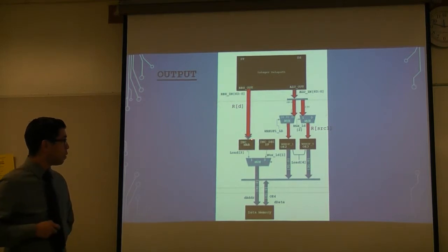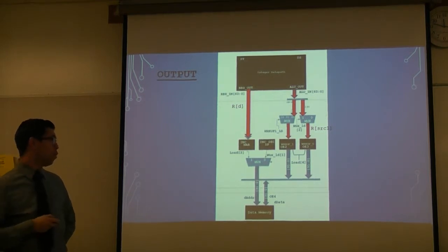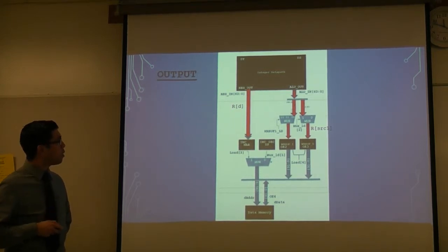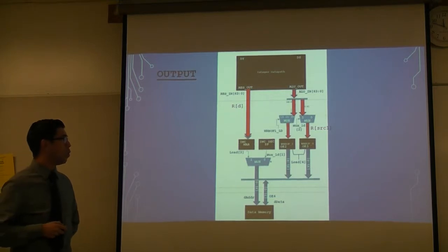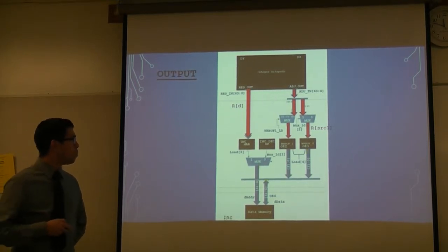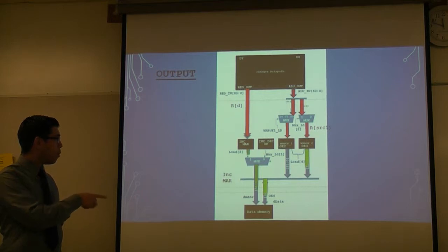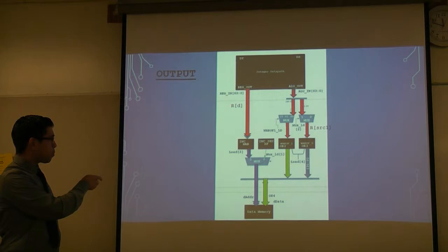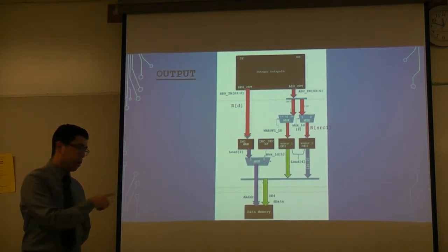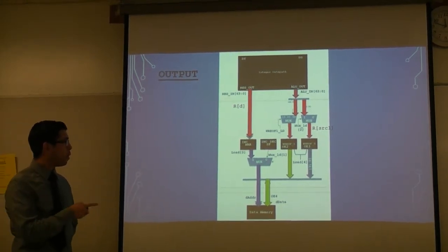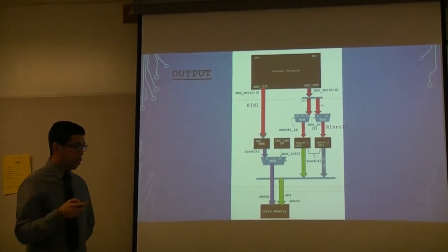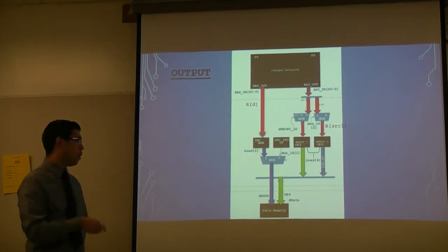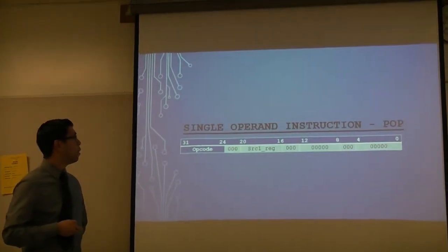So that goes into the memory address. So saying, okay, we need to put that eventually into here. So this is where it's going, and then the ALU out tells us our source 1. Those are the only two that are being used. So first, the WR buff gets loaded, and then there's the address of that one. We increment the memory address register, the MAR, on that one also, and we output the WR buff 1, which is the upper most significant 32 bits. And that gets written for the output.